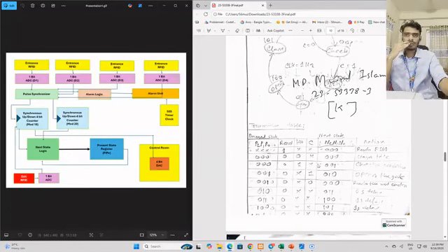We don't have any output from this FSM. Basically these are states, and according to these states we need to perform actions, such as if we reset the whole state machine, it will reset the whole FSM. On the 000 state it stays idle. On 001 it checks the conditions, on 010 it opens the gate, and on the 010 it resets the mod.